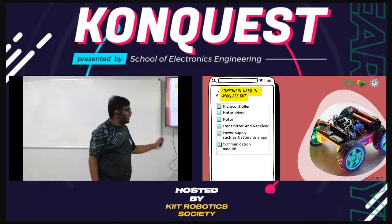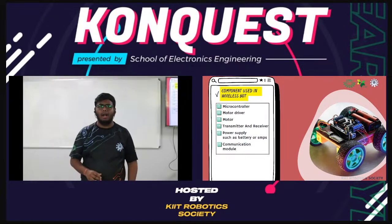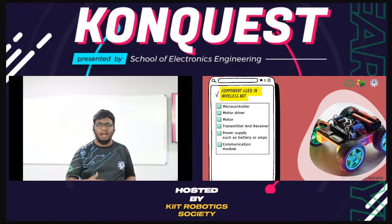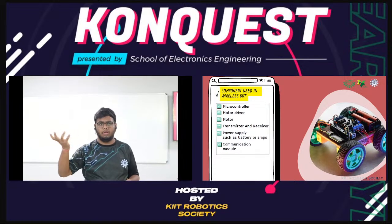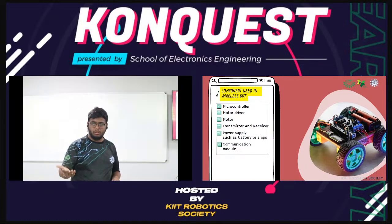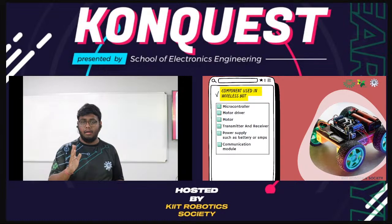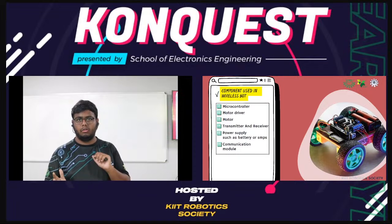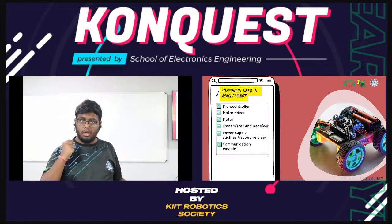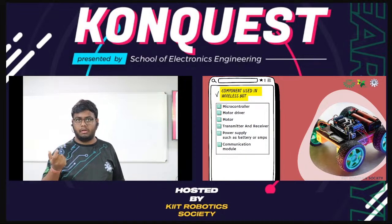The other thing, in the wired bot, we are directly pushing the buttons and supplying 12 volts or some voltage to the motors. But here you can control the voltage provided to your motor. In the wired bot, it's not in your hand to control the voltage. But in the wireless bot, you can actually control the voltage, in how much speed, in how much RPM your bot should run.